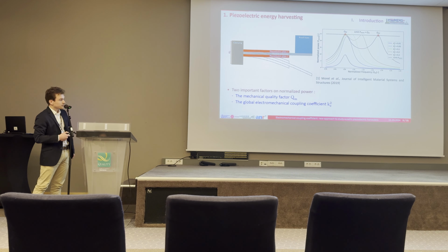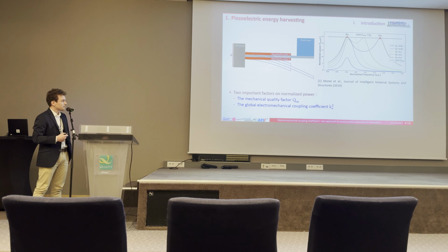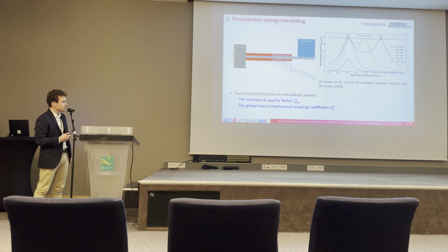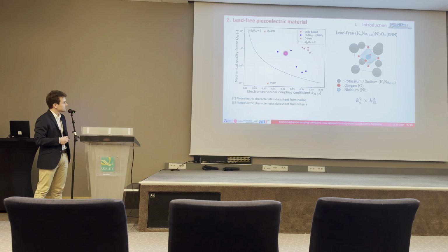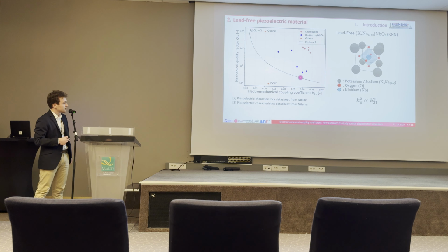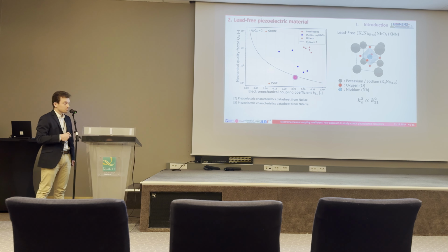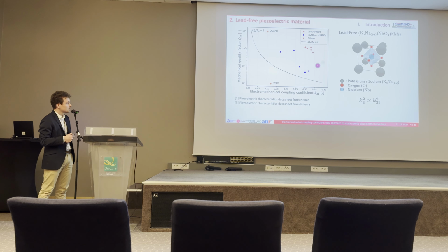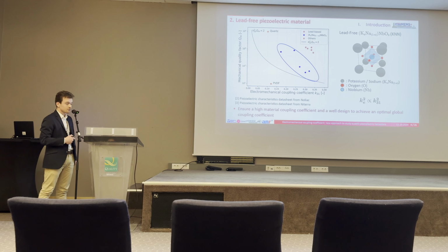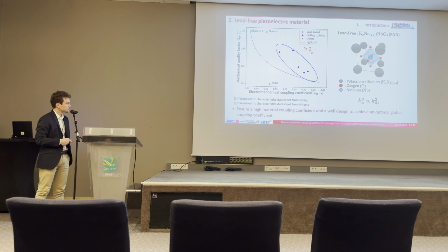So we need to increase this coupling coefficient, and for this we can work on material and design. For the material aspect, here you can see a graph with the mechanical quality factor by the mechanical coupling coefficient. We can see that there are some point clusters here, the lead-based, which are PZT, maybe the best material for piezoelectric energy harvesting, and here some points for lead-free piezoelectric materials.